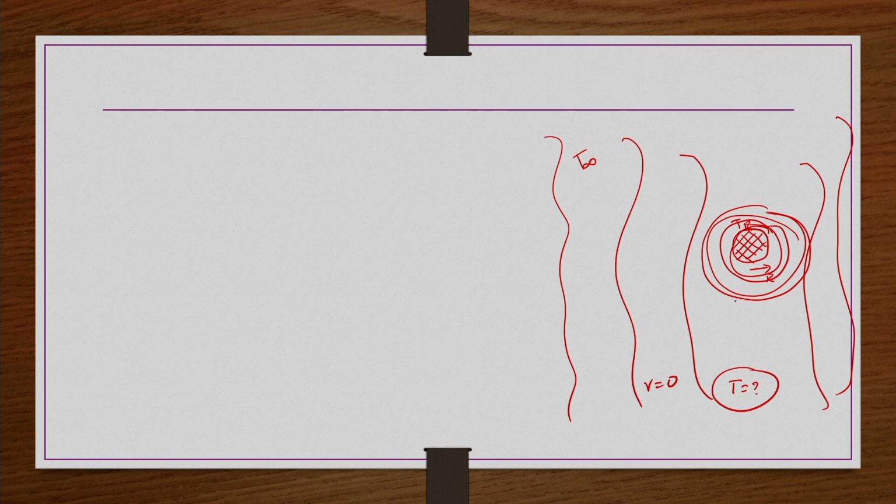So, for this case, how is T changing? The conduction would be dominated in the radial direction only, because there is no rotation. In the theta direction there will not be any transfer of energy, because there is no rotation of the sphere. Similarly in the phi direction also nothing is happening. Whatever the transfer is, it is radially transferring to the surrounding fluid. That is the reason temperature is a function of r only. What is that function of r? That is what we are going to find out now. Once we have the temperature profile, you can find out the Nusselt number. This you might have studied, it is equal to 2. So, that also we do by derivation.